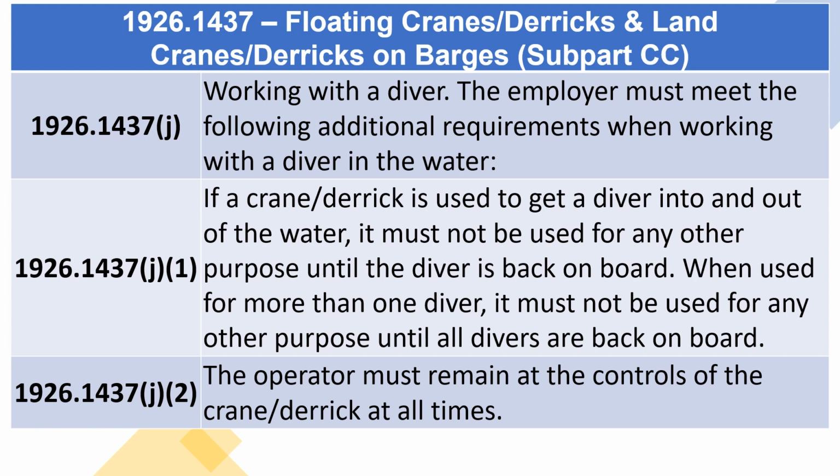1926.1437(J), working with a diver. The employer must meet the following additional requirements when working with a diver in the water. 1926.1437(J)(1). If a crane/derrick is used to get a diver into and out of the water, it must not be used for any other purpose until the diver is back on board. When used for more than one diver, it must not be used for any other purpose until all divers are back on board.